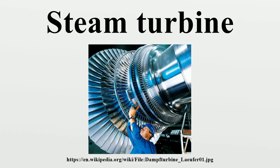Blade design challenges. A major challenge facing turbine design is reducing the creep experienced by the blades. Because of the high temperatures and high stresses of operation, steam turbine materials become damaged through these mechanisms. As temperatures are increased in an effort to improve turbine efficiency, creep becomes more significant. To limit creep, thermal coatings and superalloys with solid solution strengthening and grain boundary strengthening are used in blade designs. Protective coatings are used to reduce the thermal damage and to limit oxidation.